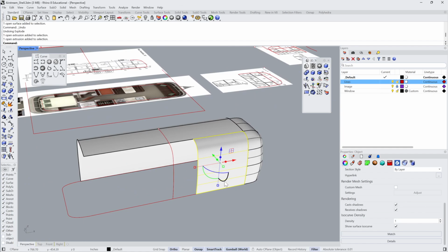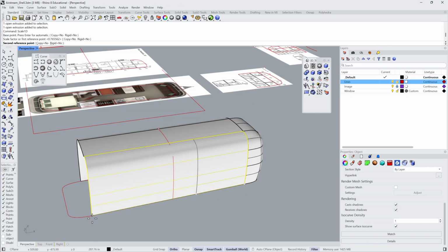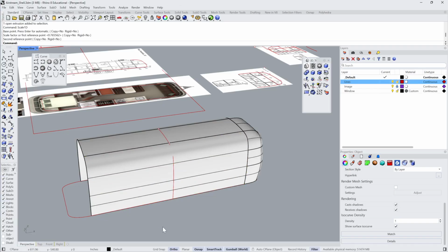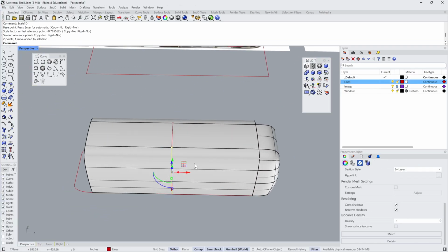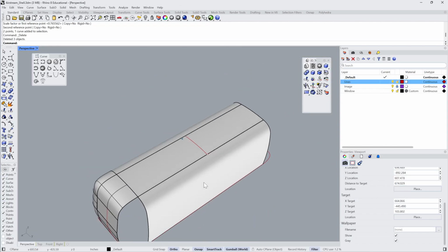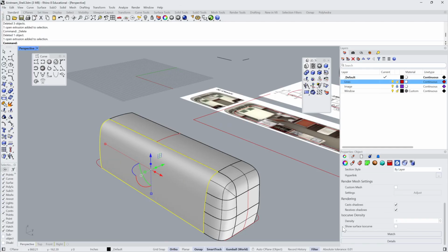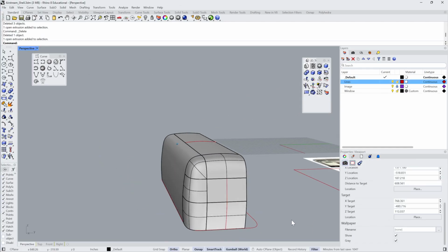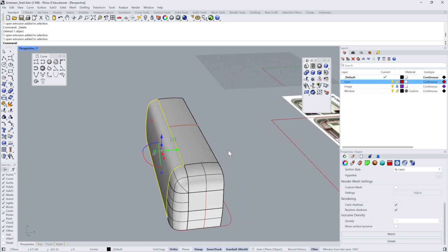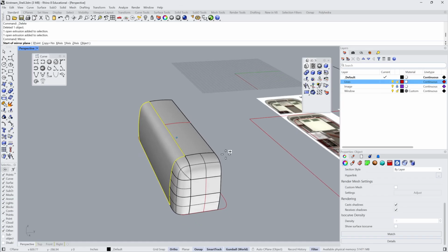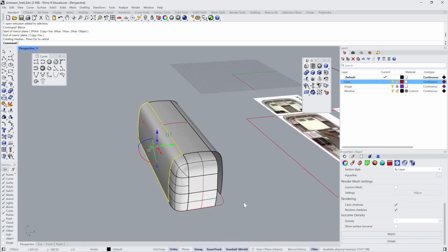So in this case, I could just extrude that and then scale 1D. And I'm bringing this all the way down to there. This is no longer our correct profile curve, and that surface is no longer correct. And if we turn off the isosurface, we still get this really clean model. And now we can use that to mirror over here, like that.